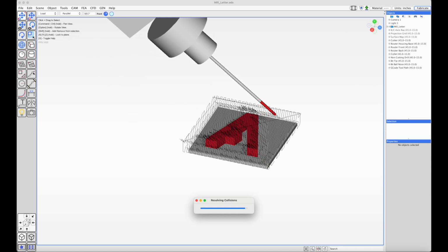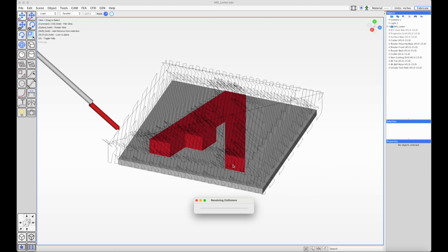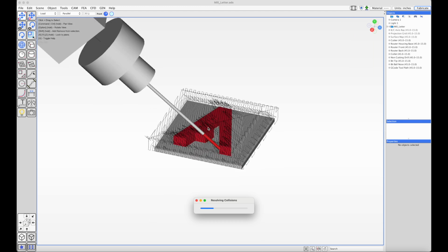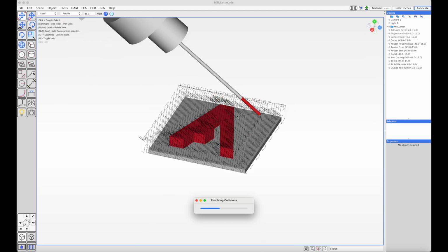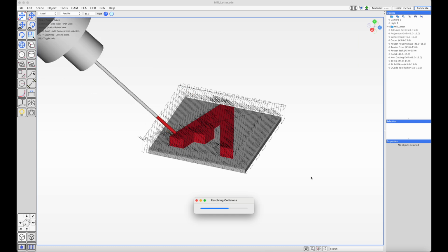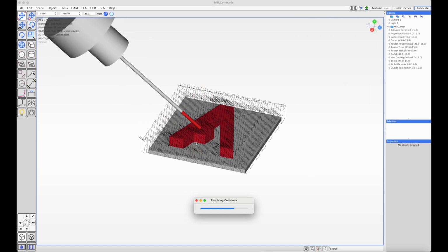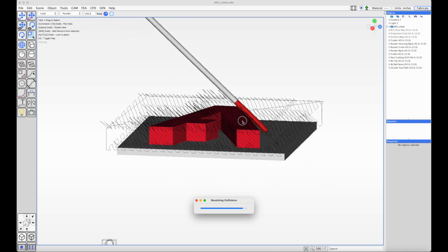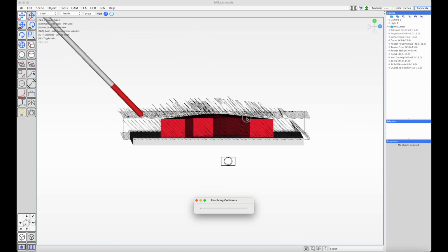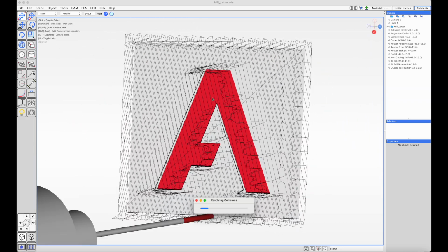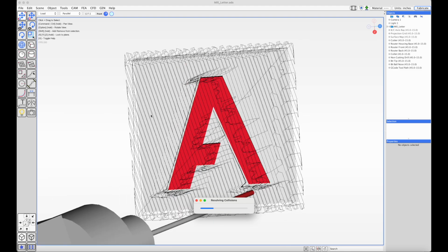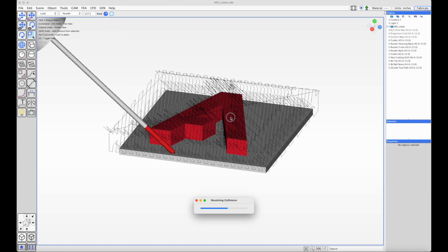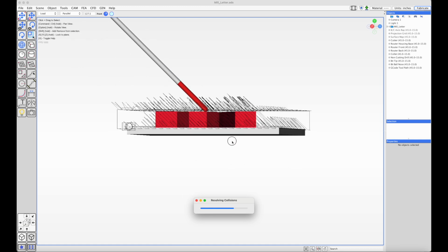So right now it's modifying the toolpath to remove collisions. Most of the geometry of the rotor is far away from the drill bit. You can see that the cutting area is in red. And it's modifying the toolpath that you can see as this line so that there aren't any collisions. Normally we wouldn't run the C at 15 degrees. This is just for illustration so that you can see. It probably makes more sense to run it at 0 degrees or 90 degrees.